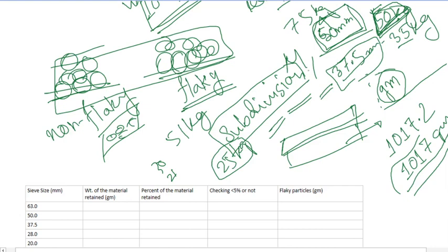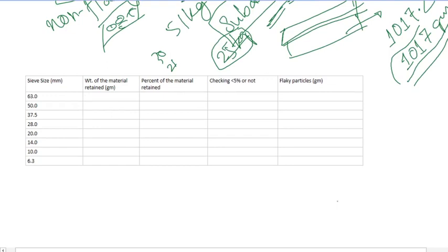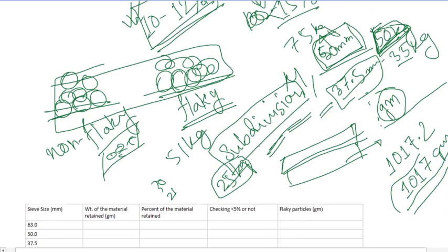So subdivision means you will have to conduct the same test by separating two samples. Say if it is 50, then you will divide it into 25 and 25 and analyze with the same procedure again to get the sieve analysis, the weight retained values, and finally combine all those values in such a way that a correction factor is applied, so that the result is the same as if it had been conducted together.